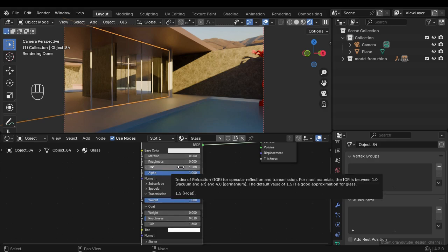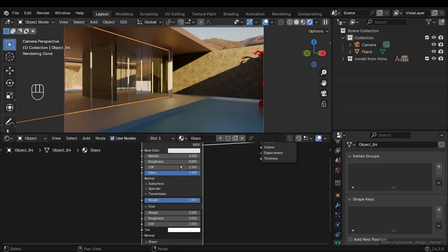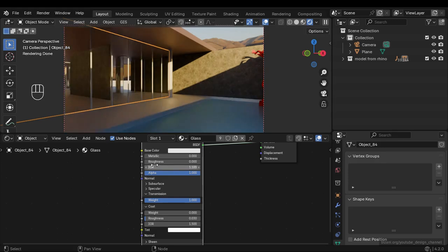The IOR level controls the direction of the light. For what's transmitted, let's just keep it very low, 1.1. And now, if I increase the roughness, this changes what's being transmitted, the roughness of what's being transmitted. While this one, I increase the coat weight to enable the coat. We can see some reflections. And here, this is the roughness of what's reflected.